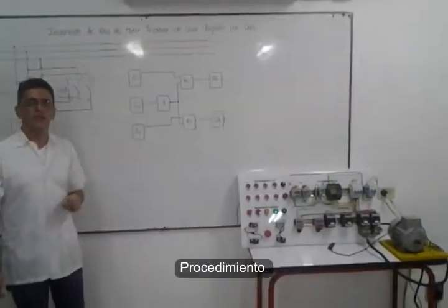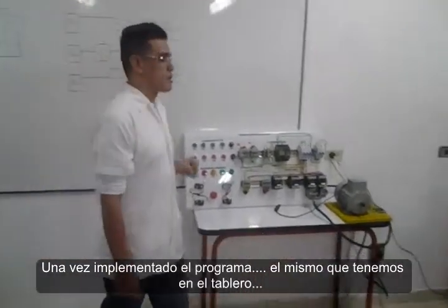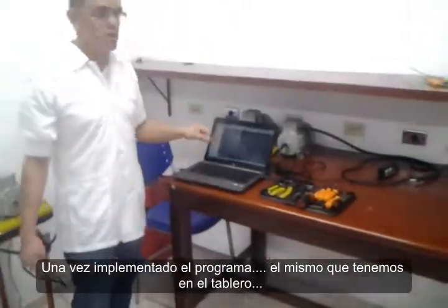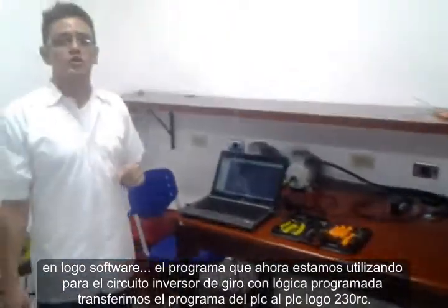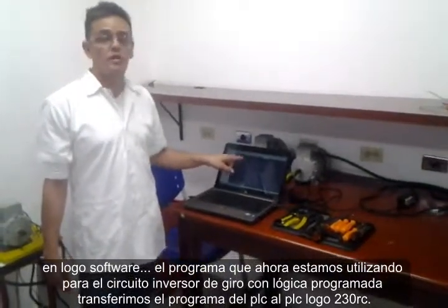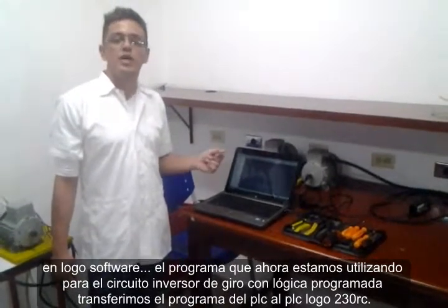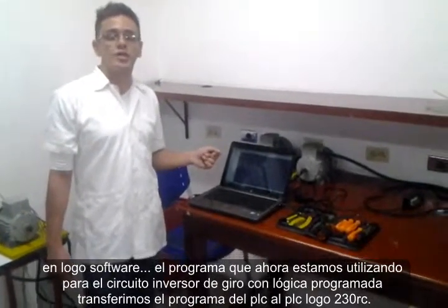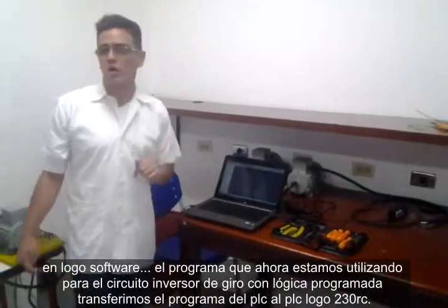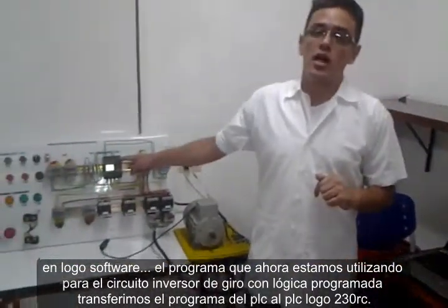Okay. The procedure. Once implemented, this is the program, it's the same scheme that we have there on the board. Once the program is implemented in LOGO! software, which is the program that we are using now, for turning the inverter circuit with program logic, we transfer the program from the computer to the PLC LOGO!. The case that we are using is the 213 RC.